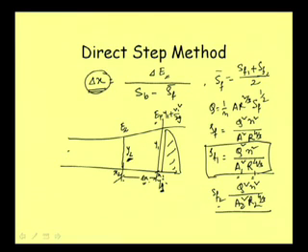So once we calculate delta x, say let us put this delta x as delta x1. So what we have got after calculation, say y2, for y2 we are getting this is delta x1. That means our purpose is served, that we know that our y1 depth is at x1, then after delta x1 distance our y2 depth will be. That we want to know. If we want to plot the profile also, now we can plot up to this point.